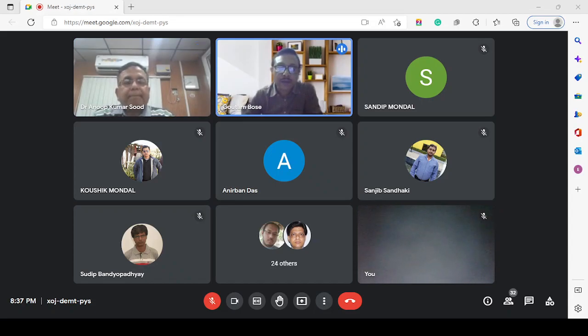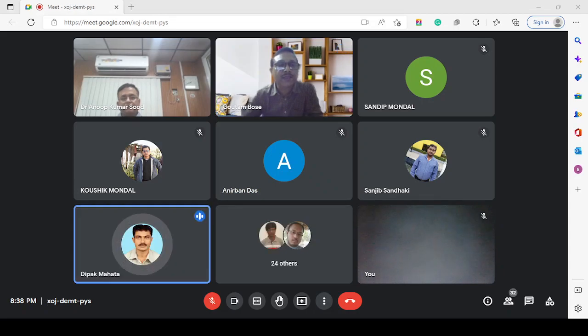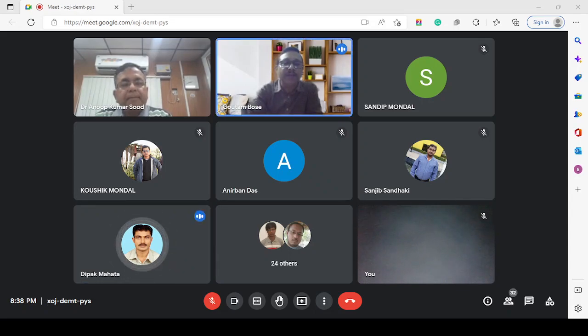nowadays what is being observed is that for a regular kind of object, when you are 3D printing, in order to make it in mass scale production, if we can place that product along the z-axis, n number of items can be prepared. The xy is the table movement, but along the z-axis, if you are making a similar kind of regular product, let's say a spur gear of certain dimensions, so if you can make say 3, 4, 5 items along the z-axis, I think that's how they are making mass production.